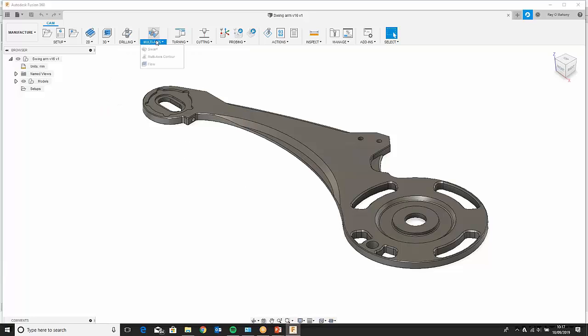We obviously have the drilling and hole recognition, but the big thing for me is the multi-axis as well. Being able to build on a 5-axis simultaneous environment within Fusion 360 is a very powerful tool to have. It gives end users who would natively be using a design componentry like Inventor a bit of freedom and flexibility to look at the manufacturing cycle as well, and alternatively, maybe look at modifying the part to suit the manufacturing process downstream.